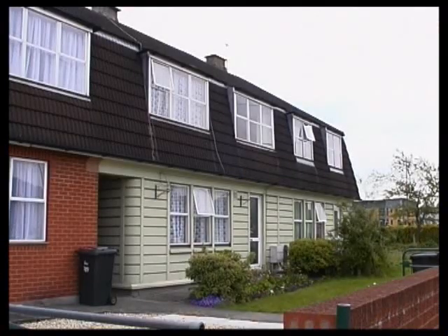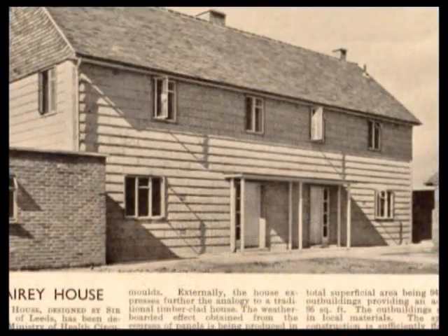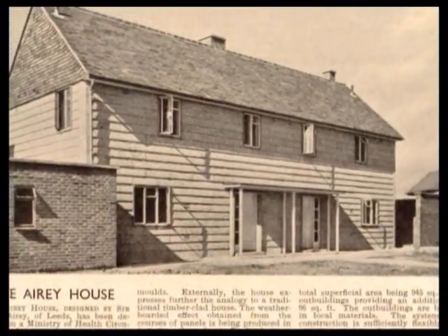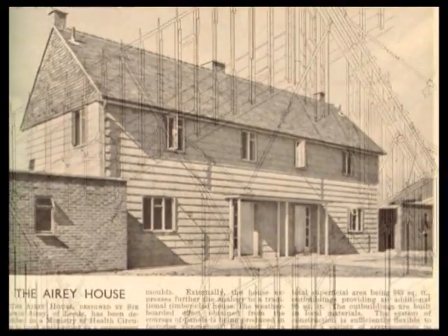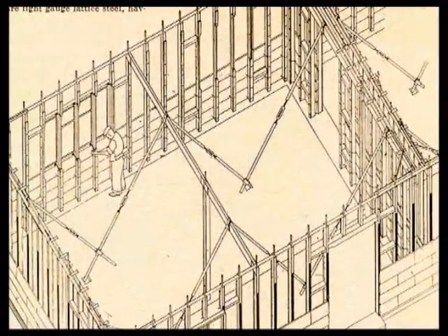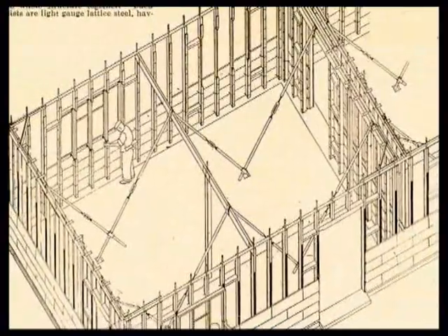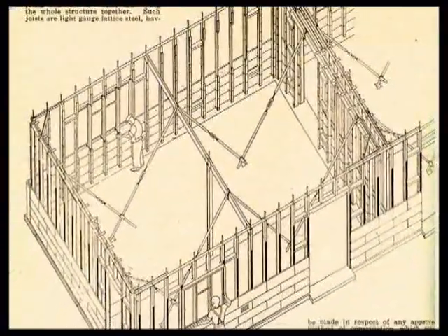Most of these houses were built on greenfield sites with good bearing capacity. On this type of ground, rafts were relatively cheap, easy to construct, and didn't require extensive excavation. In those days, foundation trenches were usually dug by hand.